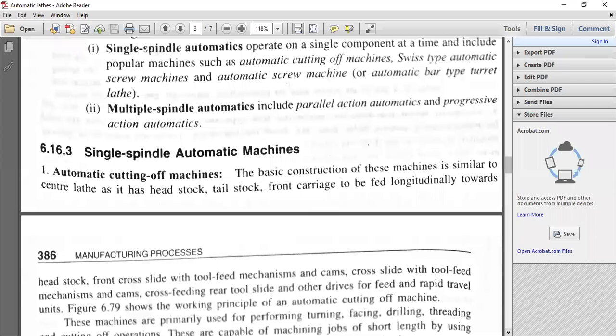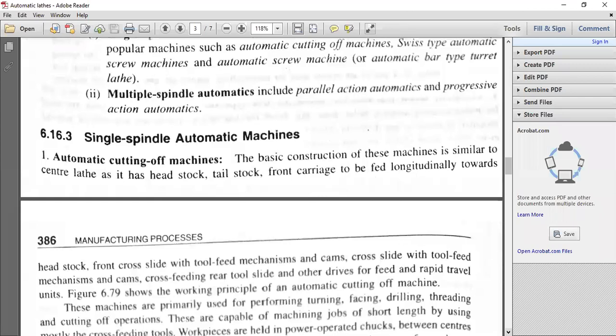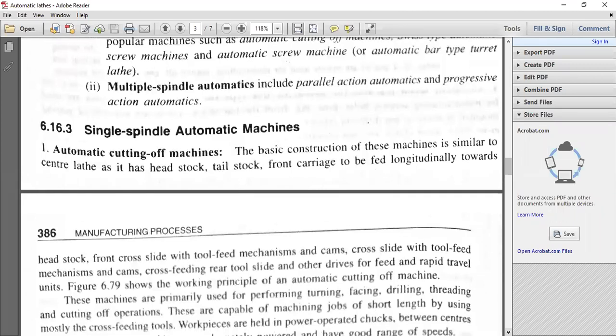Suppose you are choosing units, you choose between G20 and G21. Or you choose between G01 linear interpolation, straight line turning, and G02 circular interpolation, not straight turning. So we have G01, G02, G03. And in between, G04 is the dwell period for machine setting. All this is there.